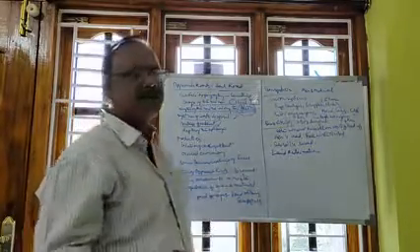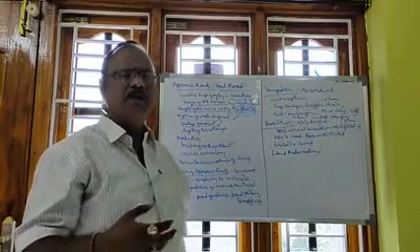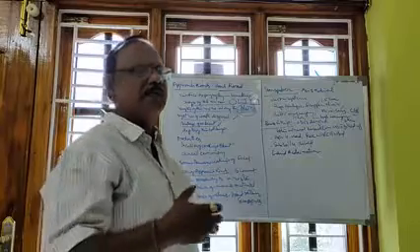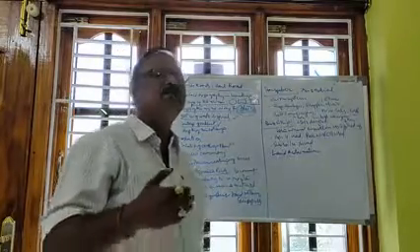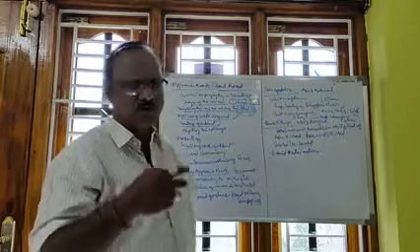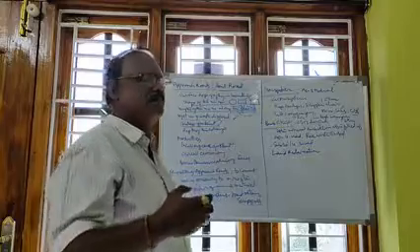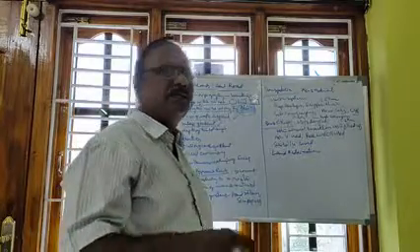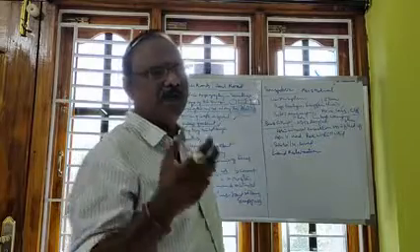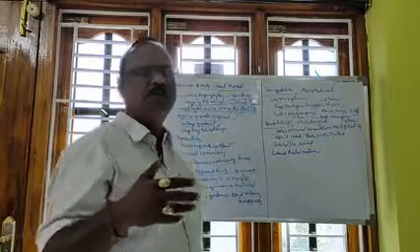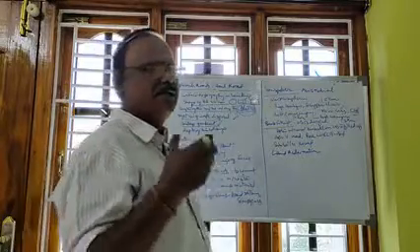So the gradient must be negotiable, maybe 1 in 10. Generally the gradient shall be kept at 1 in 10, 1 in 11, 1 in 7. So approach roads with very little gradient are used. But when you use 35 tons dumpers, the gradient can be a little higher, maybe 1 in 8, 1 in 7.